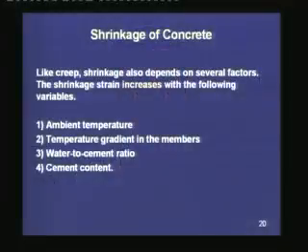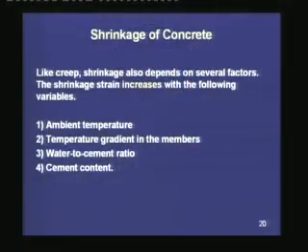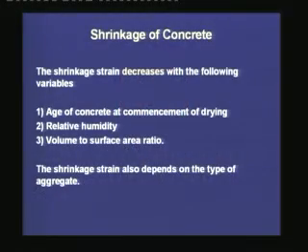Third is the water to cement ratio, and if the water to cement ratio is higher, it is a low grade of concrete, loss of moisture is high, and hence the shrinkage is also high. Cement content. Just like creep, if the cement paste to aggregate ratio is high, then the shrinkage strain goes up. The shrinkage strain decreases with the following variables.